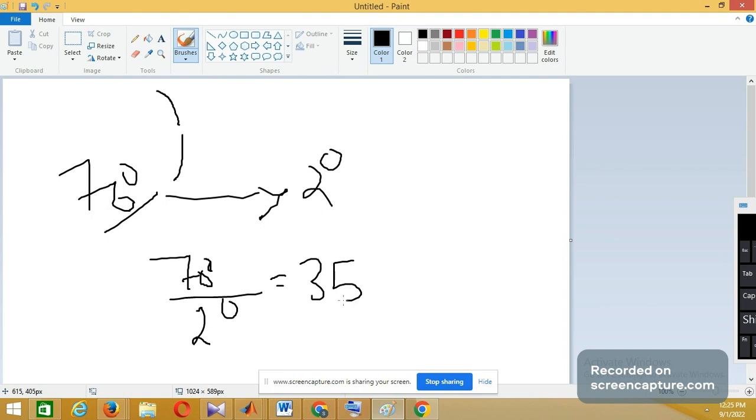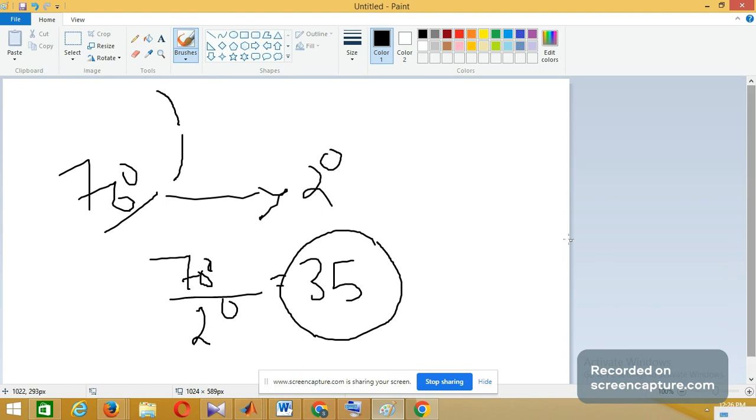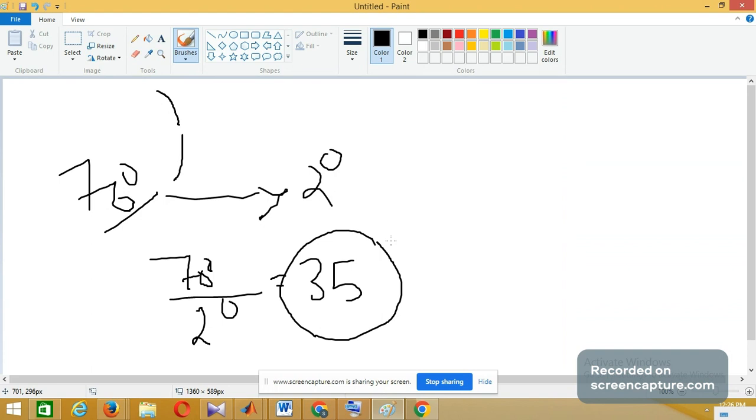So you should not write SJMP back. You should keep this 35 as a count in some register, and wherever you have SJMP back, you should write DJNZ. For example, if you have kept R3, write DJNZ R3, loop. See, this is what you are supposed to do. So I hope you understood. Let us say clockwise, 70 degrees, for one step of 2 degrees you are supposed to do it 35 times. So 35 should be kept as count, and that many number of times you are supposed to do it.